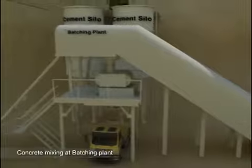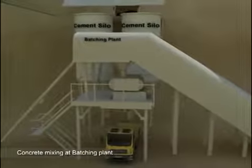Aggregates from pre-cooled storage bins are now carried via a closed conveyor to the batching plant weighing mechanism and further for mixing. At the batching plant, aggregates are mixed with cement coming from the cement silos and chilled water in the required proportions to make a concrete mix of the desired consistency. The concrete thus made is transferred into the concrete bucket placed on a truck that carries it to the dam location.